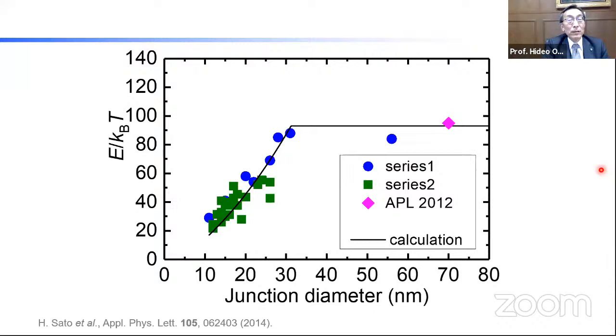So the rule of thumb here is that you need to divide the number that I'm talking about here, junction diameter, by approximately 3, in order to compare it with those advertised gate lengths. So if I say 10 nanometer, that's almost close to 3 nanometer gate lengths, and not many have demonstrated 3 nanometer gate lengths. Okay, so the question is, how do we do this?